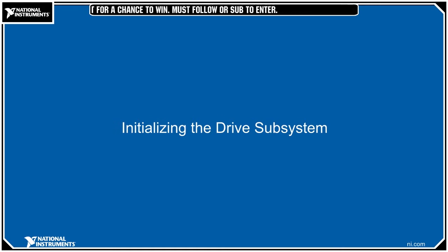The operation control, the .ctl, is just a control file. This is a type def, which means that when you edit this, if you have it used anywhere, if you've copied and pasted it into another front panel, it will update as well. So this defines the operational modes of a controller.